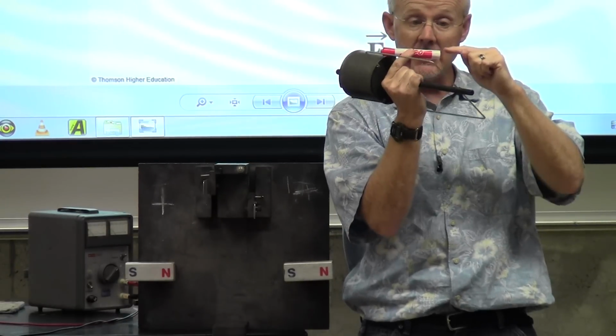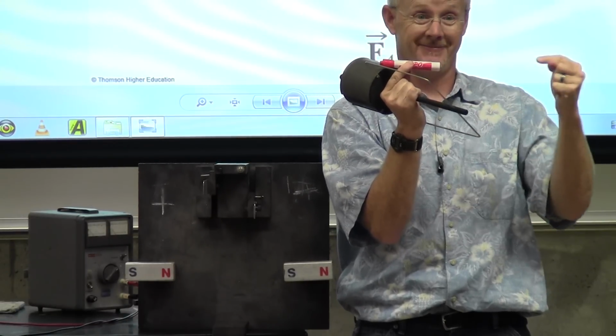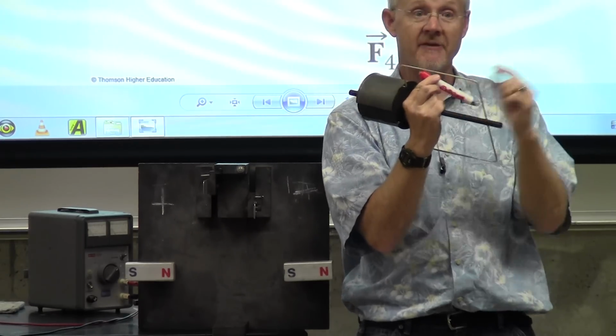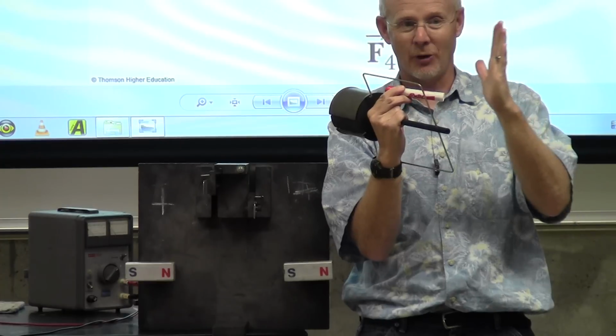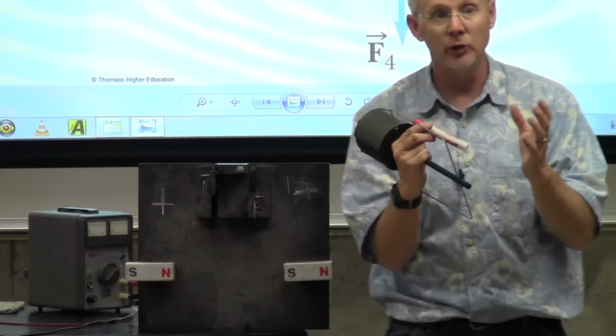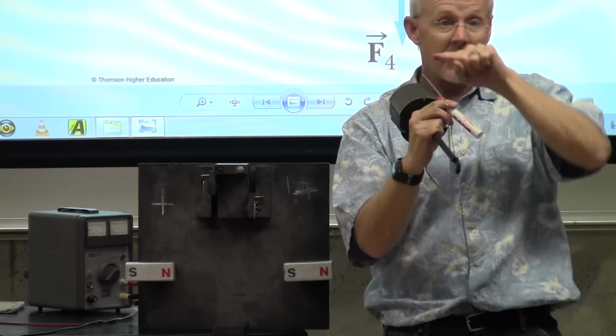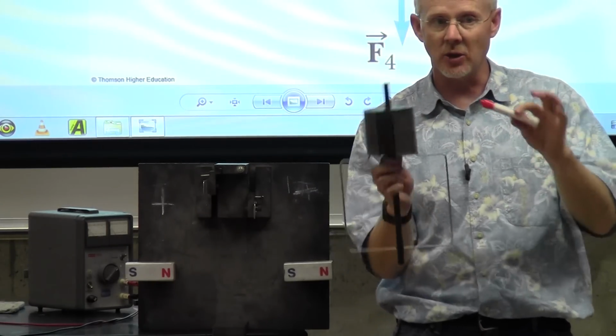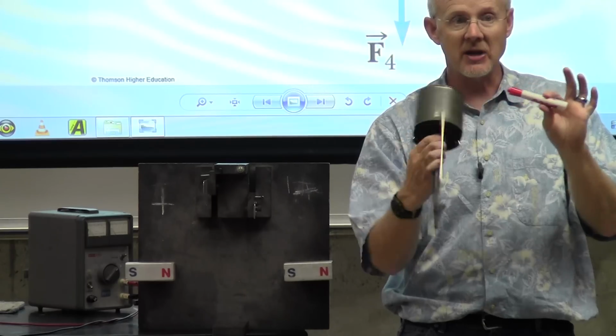And then behind it is a spring. So as it rotates, it wears out the graphite. But the spring keeps pushing more graphite close. And graphite is a nice dry lubricant. As it wears, it actually then has a very, very low resistance. So it's lubricating, and at the same time as it wears.